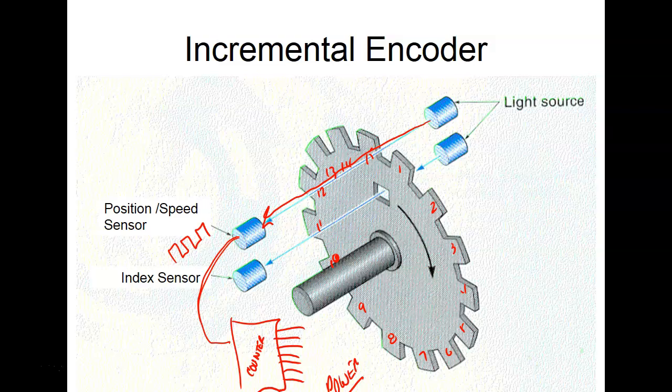So they look like they're absolute encoders, but they're not. They're incremental encoders, but the counters are part of them. But the problem is if you lose those batteries on that robot, if you don't keep them up, we say we lose the origin. The robot doesn't know where it's at anymore, and you have to re-origin the robot. Most of the robots have marks on them where you line them up and say, okay, this is equal to 0. So they are absolute encoders. They're technically called battery backed up absolute encoders because they're actually incremental encoders, but they have the counters as part of the encoder.